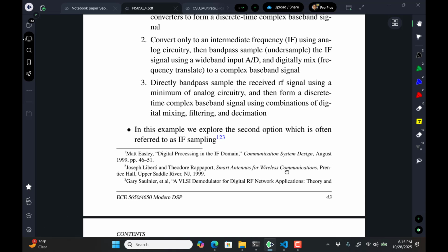The system I was working on for the Blue Moon project was at S-band, which is at 2.602, whatever it was. I had the frequency in my head from setting up equipment, but the exact number is not there anymore right now. But at any rate, that's the carrier frequency that carries it over from one antenna to the next. But then we come down to an intermediate frequency to get it shifted closer to complex baseband, where we're going to process it and then process it yet again.